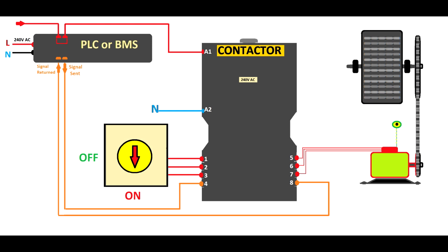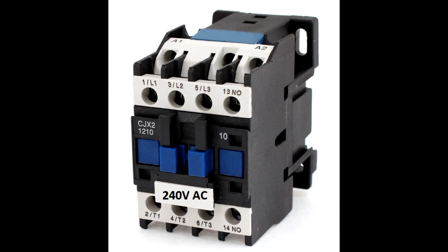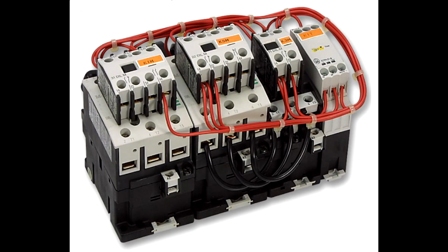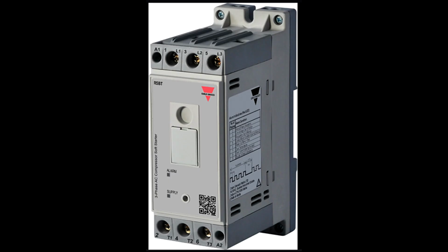Probably this motor is direct online start. That's not very recommended, because you'll put a lot of stress onto the motor, the wires, the fan, and also the belts. People use star delta, and you will understand how star delta works if you watch some of my other videos. This is the star delta. You see you have a time delay relay and 3 contactors which allow you to run the system.